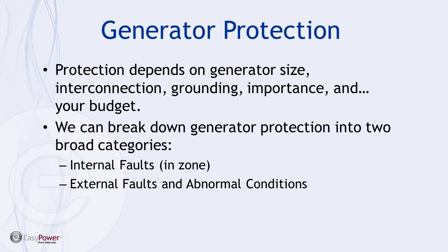So if you have a large generator in your system, that's a major investment. It's a long lead item, and so if you're going to have damage to the equipment or to the generator, you want to minimize that to the extent possible. Ideally, if you have a winding fault, you want to be able to just replace that winding and not have to restack the stator core due to a lot of damage to the core. So those are the goals.